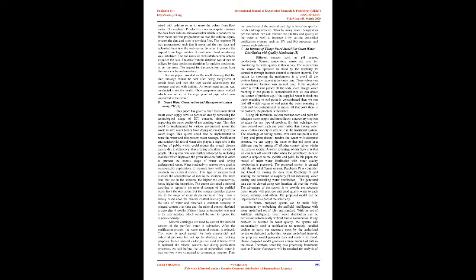Analysis, design, and development of an IoT-based water management system for residents. This paper describes the water management system's design and construction details. Tank 1 is fed from the reserve tank, and the pump motor is turned on and off automatically. Tank 1 has two solenoid valves which automatically flow water in two ways: one to a water filter tank, and the other to tank 2.